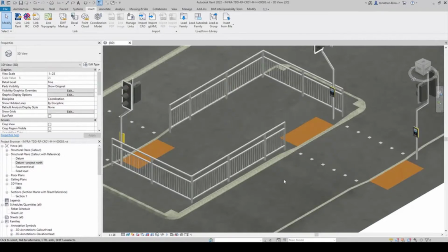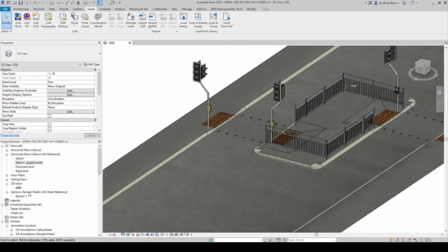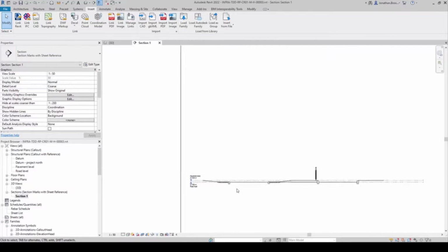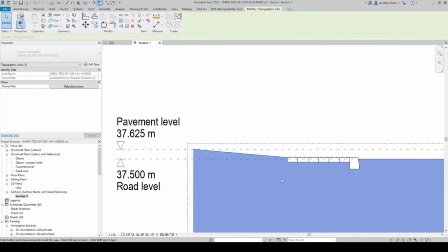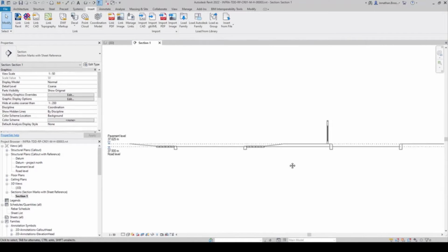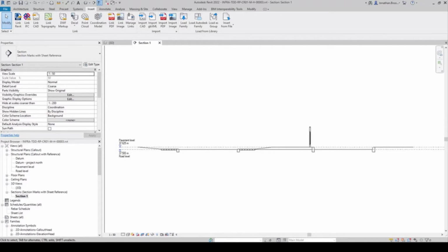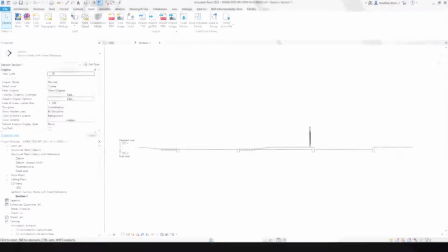The surface can now be used inside of various Revit views, including 3D isometric views, sections, elevations and plans. It can also be used as a host for objects to follow using the railing tool. This is the perfect solution when designing fencing that needs to follow a proposed or existing terrain.